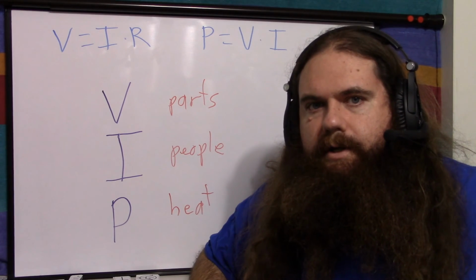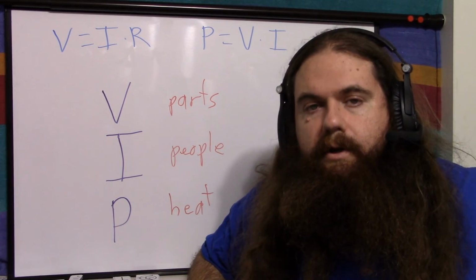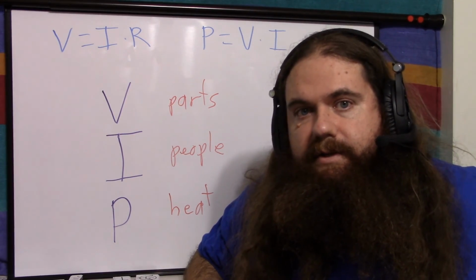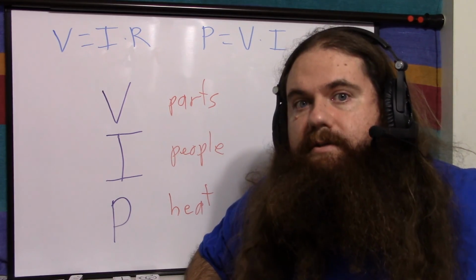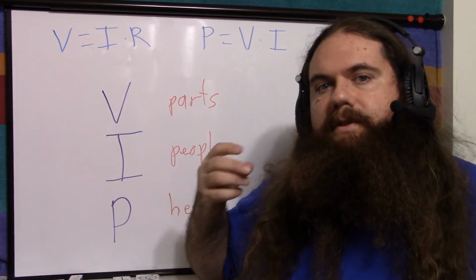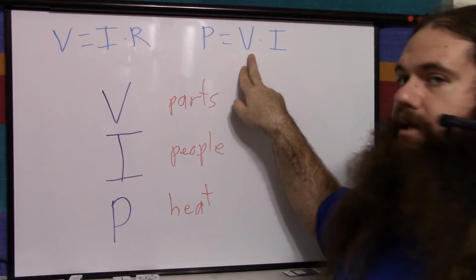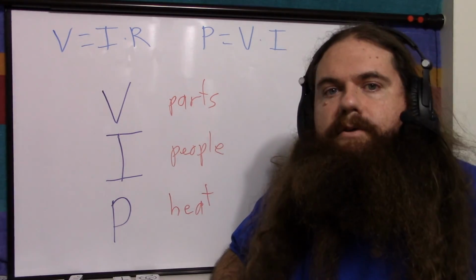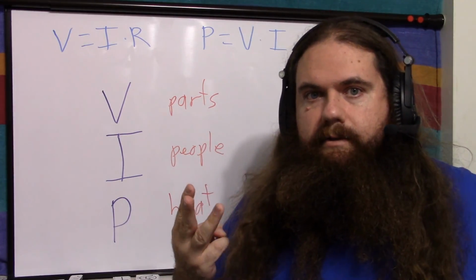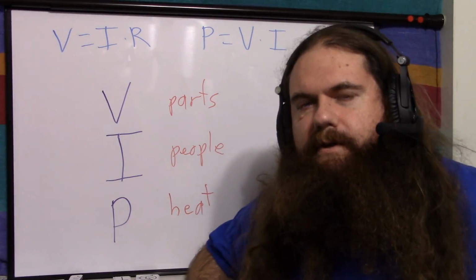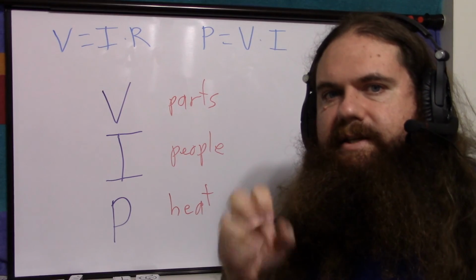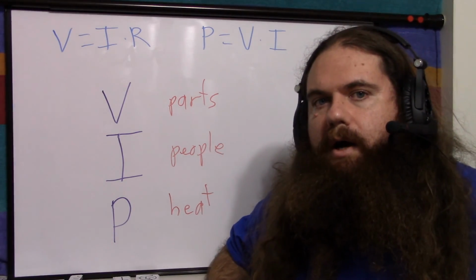So if you've ever overclocked something like a CPU in a computer, overclocking means you run it faster than it's supposed to go. But if you run it too fast, then it becomes unstable. It's perfectly safe, it just doesn't work. But to make it work better at a faster rate of operation, you increase the voltage. This generates more heat because increasing the voltage increases the power. That's heat. So you have to cool it better. And then you get liquid cooling, liquid nitrogen cooling, all this other stuff. But there comes a point, even if you had perfect cooling, even if you could rip the heat out of there the second it's made, the instant it's made, if you increase the voltage too high, you'll break it.